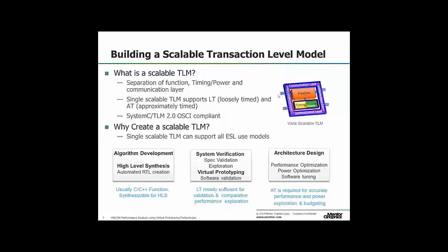As well as this split of a model, it's also possible to run a platform in what's called LT, loosely timed mode, which enables fast simulation and is most appropriate for running real software on. It's also possible to switch to what's called AT, approximately timed mode, where the simulation runs much slower, but in this mode we're capturing all of the timing and power information so that we can analyze that data.